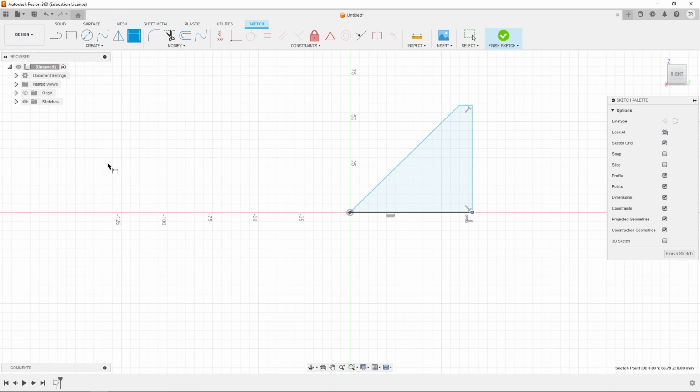I'm going to click on it. The way we know this tool is active, notice the cursor. It's now black and has the little picture that looks just like that button. The way this is going to work, and again, this is very flexible, we can click on something and then click the dimension button, or we can click the dimension button and then click on a part of our sketch. There's a lot of ways to do it. I'm going to click on this line.